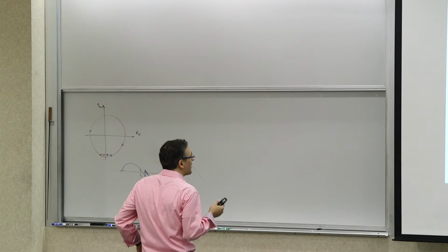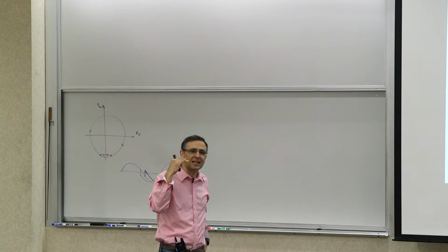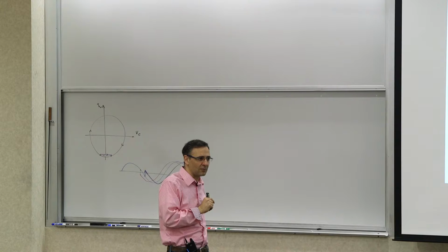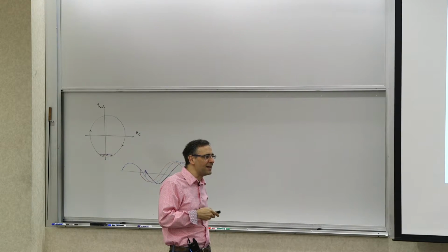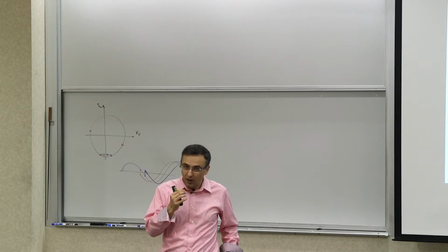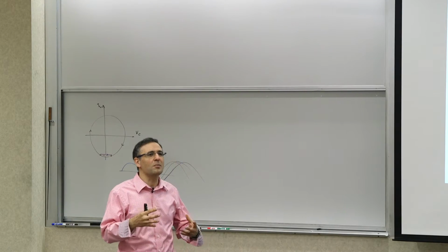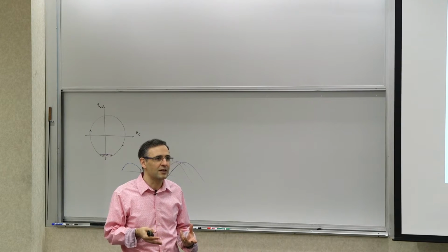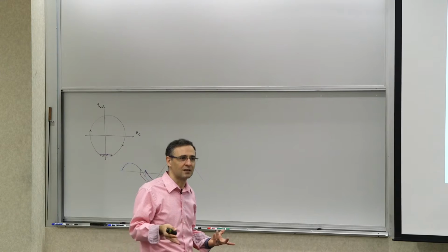Intuitively, why would the RMS value of the ISF be the parameter that matters? If you think about it, it should be rather clear, because we said it's the noise in the vicinity of the integer multiples of the frequency of oscillation that come into play. And they were controlled and adjusted by different coefficients of the ISF, the Fourier coefficients of the ISF. Now, the sum of the squares of all the coefficients of the ISF, by the Parseval equation, is the RMS value, right?